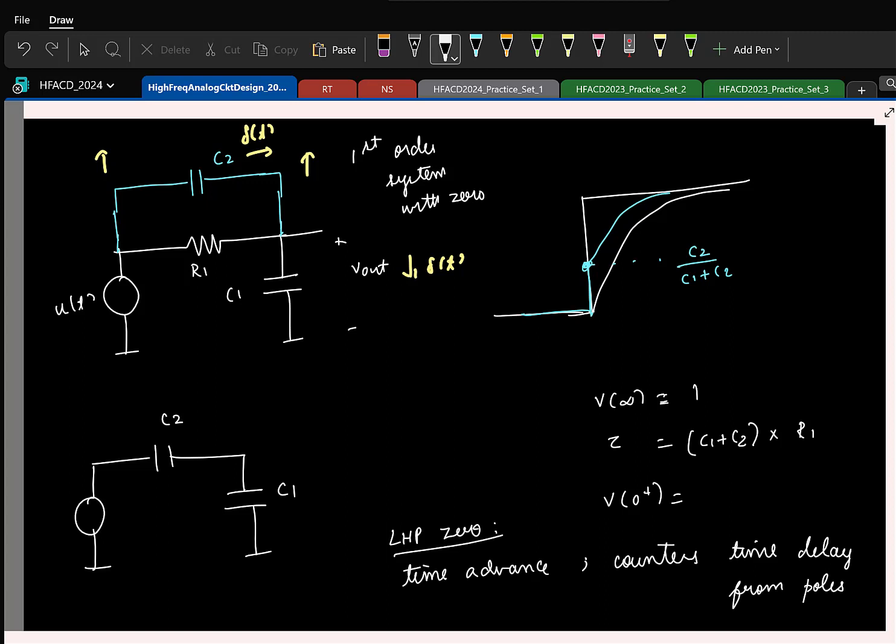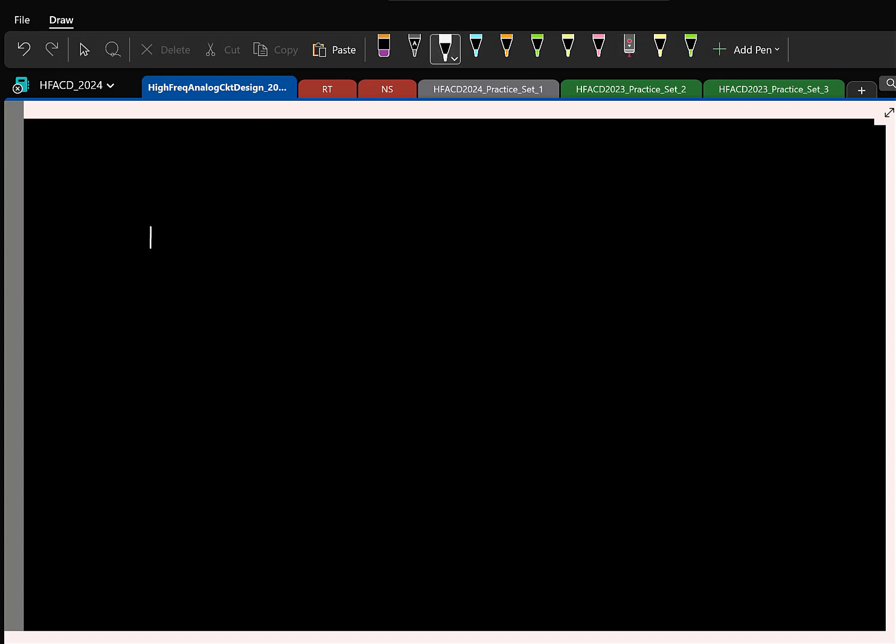Time t equal to 0 plus, capacitor will be shorted. Yeah, that is correct. I mean, see, there are fine points, right? Okay, I understand what you are getting at. So his question is, first you think why is that true? His question is at t equal to 0 plus, you might have learned capacitor acts like a short circuit. So why is the output jumping instantaneously? Why?